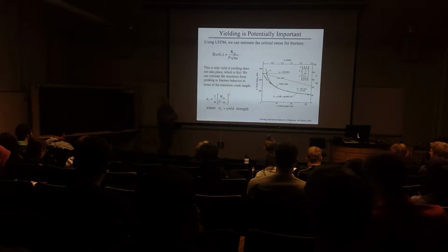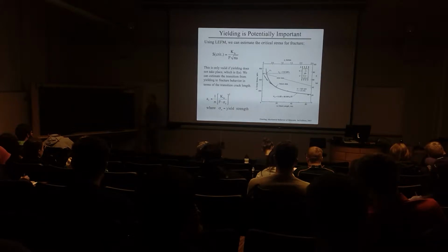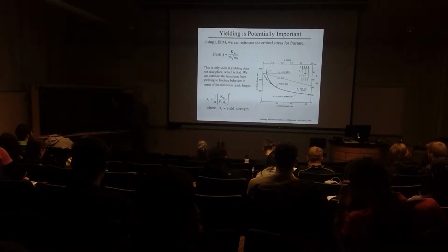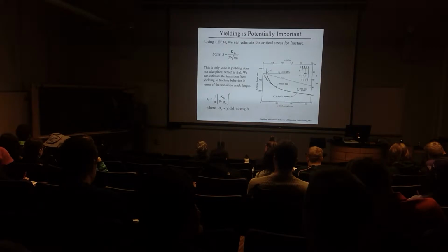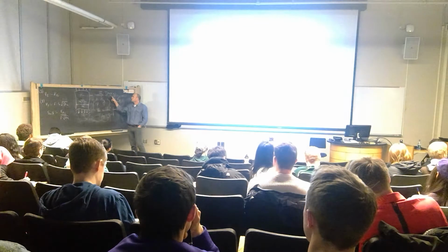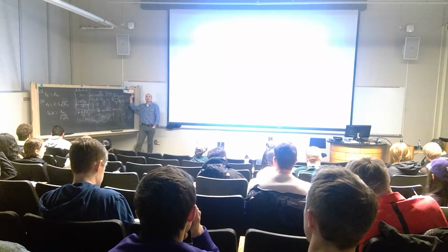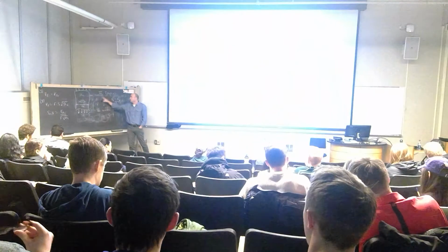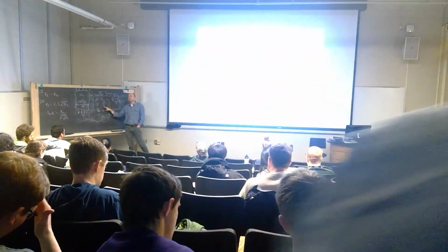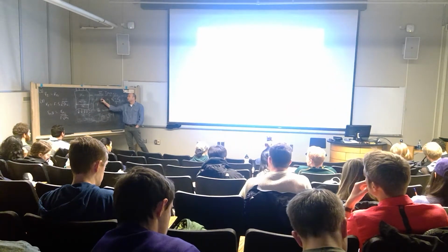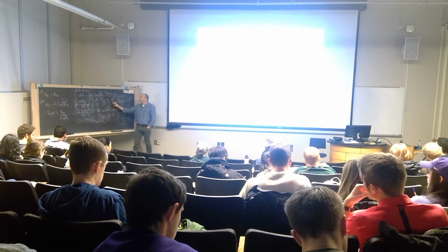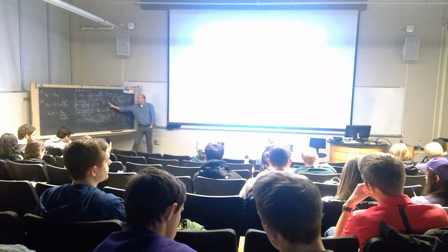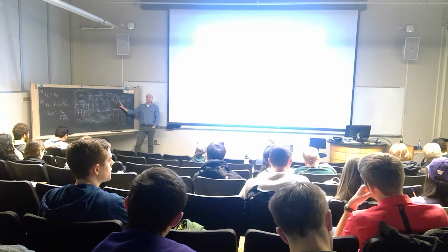And so then there's another criterion that we would use to talk about how that particular structure will likely behave. So for those of you who have taken 220, you'll be introduced to Tresca before as a failure criterion, which is just really a maximum shear stress failure criterion. It assumes the material is ductile, and so what we're doing is comparing a critical value of stress, and in terms, this is actually the shear strength of the material, the yield strength under uniaxial tension divided by 2. And that quantity is set equal to the principal stress difference divided by 2.